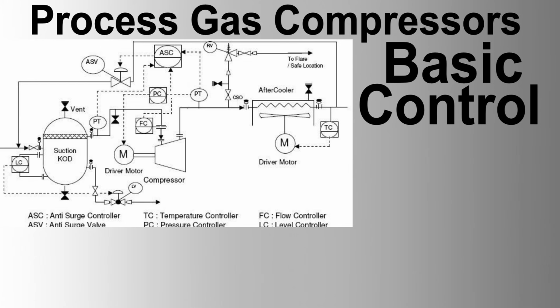2. Interfaces with the MCC, motor control center. A. Signals to the MCC. Start-stop commands, digital signals from the DCS to initiate or halt the motor. Speed reference, analog or digital signal, typically 4 to 20 milliamps or 0 to 10 volts, indicating desired motor speed. Fault signals, digital signals indicating motor or VFD faults to the MCC.